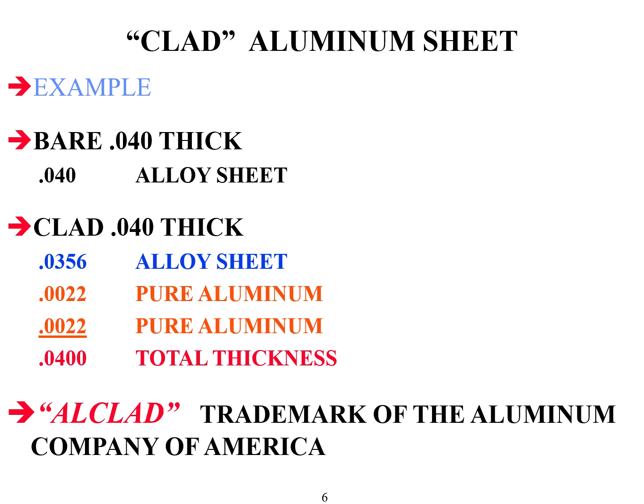Now there is a difference. In this case, if it's a 40 thousandths thick piece of bare alloy, then it measures a true 40 thousandths. However, if it's a clad sheet, on each side, a little over 2 thousandths is used to apply the pure aluminum, leaving your alloy at basically slightly over 35.5 thousandths. So if it's a clad sheet, you do lose some strength as compared to a bare sheet of alloy. But the cladding is there to help prevent corrosion. It's engineered into the mix.